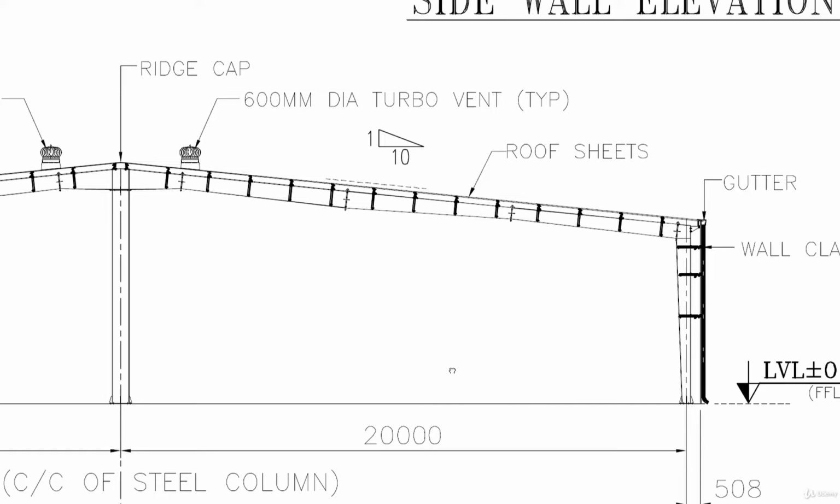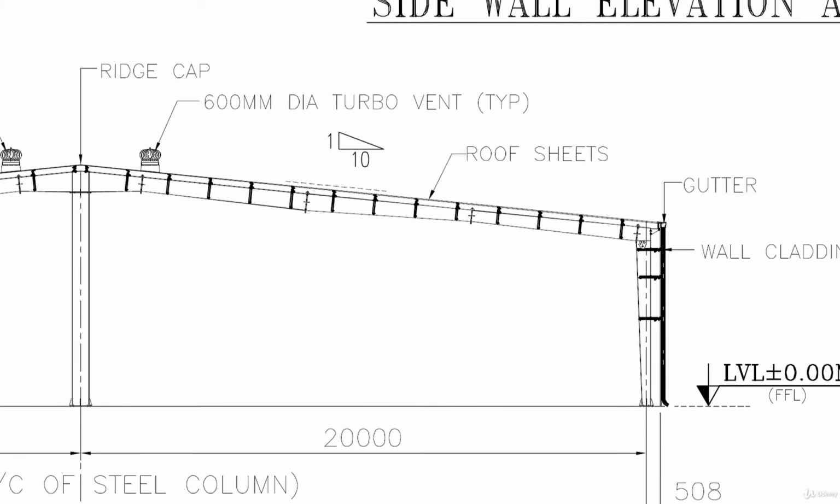To save structural steel, we have an option to put steel only in the areas in which the bending moment or shear force is high. Here at the beam column junction, as this is a fixed end condition, a large amount of moment develops. If we draw the bending moment diagram, which we will see in the last result lecture, you will see that the bending moment diagram is somewhat like this.